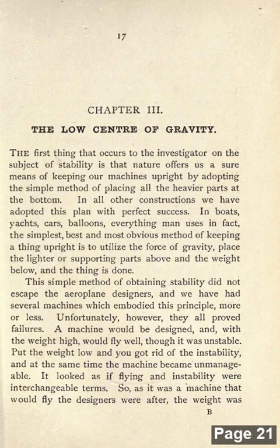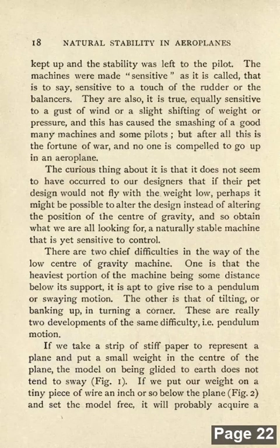Put weight low and get rid of the instability, and at the same time the machine became unmanageable. It looked as if flying and instability were interchangeable terms. So as it was a machine that would fly the designers were after, weight was put low. Natural stability in aeroplanes was kept, but the stability was left to the pilot a lot.